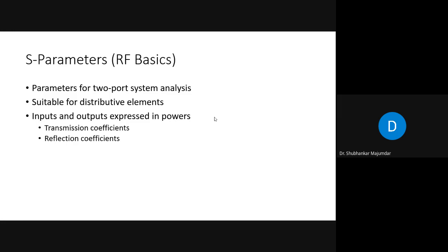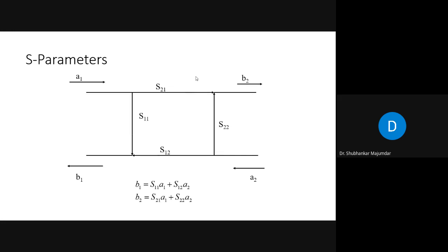These three waveforms we see at the node. If it is S11, we are getting the reflection at port 1 only. If it is S22, it is reflection at port 2. If it is S21, that is how much power wave has been transmitted from one port to another port.